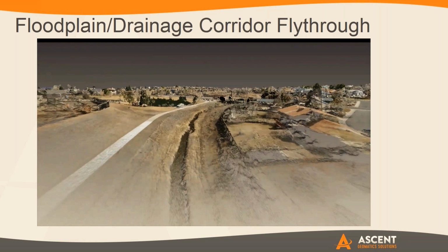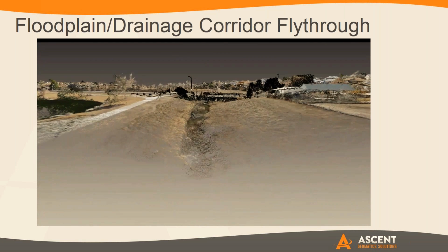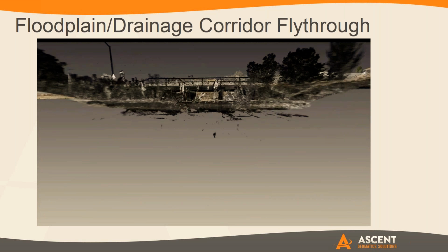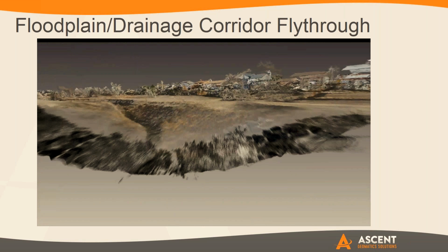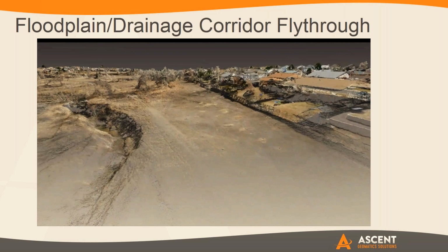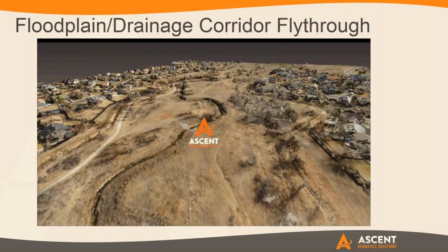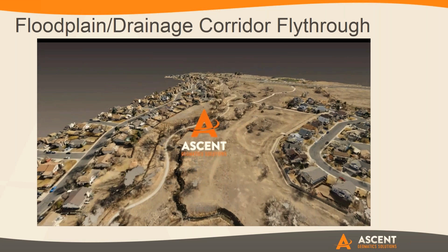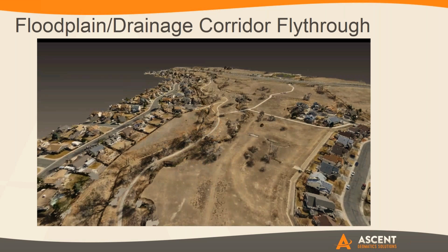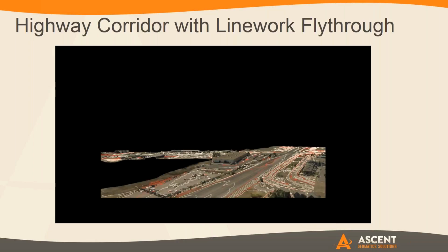So we gave them the all-over feel for the actual floodplain via the photogrammetry that you can see we're flying through now, and then got that really design-level detail that you can see right here at the bridges and the culverts. That way they can do the real design and understand what the flow rate through there is, what type of structure, what type of replacement we have to put in there. And with this, you can actually get levels of detail that I think we'll dive into in a second that you just couldn't get with conventional methods.